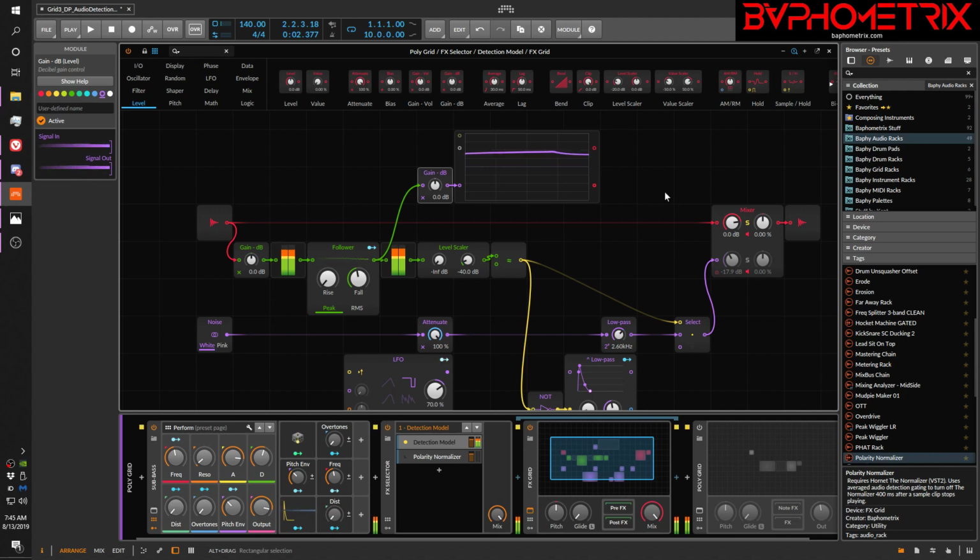And then normally, and I do say normally, if we were trying to use this signal straight out of the envelope follower to trigger logic, this line would have to be above the 50% mark to actually trigger logic. But we're not quite doing that sort of comparison.